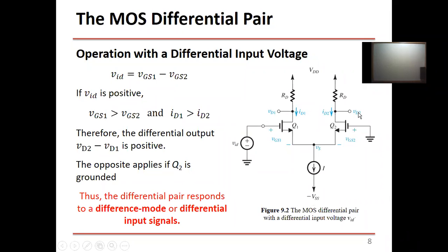And the reason that we don't desire coupling capacitors is that if you fabricate them inside an integrated circuit, they are going to be very large, they will consume a very large size in the IC, okay? And you'd like to reduce the size of the integrated circuit as much as we can. So let me give you an example. For example, if you'd like to design a very small capacitor of 10 picofarads, you might need at least 10 times the area of a transistor to design one capacitor of just a small value of around 10 picofarads.